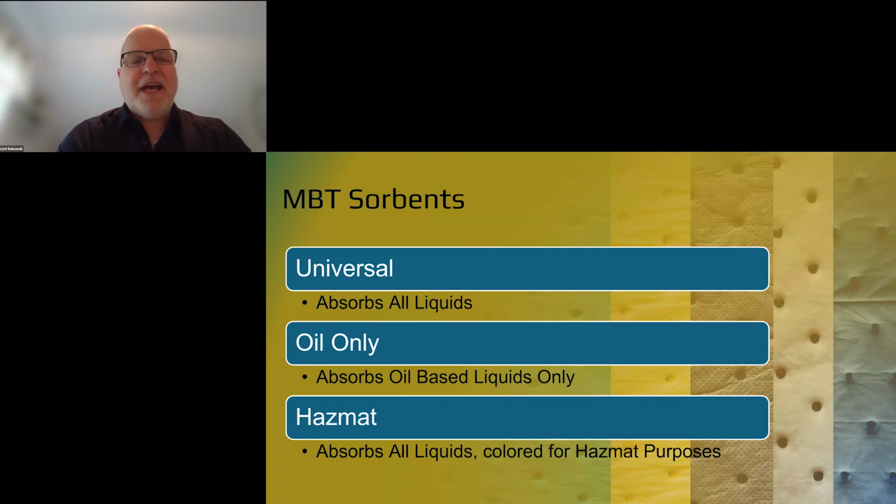Oil only is simply that. It's oil only. 99 times out of 100, this product is white and it absorbs oil-based liquids only, so anything petroleum-based. It'll repel anything water-based or any chemical or solvent. A lot of times you'll use oil-only product in outdoor applications. It may be in an environmental cleanup, or at your facility in an outdoor application like storm drain containment or possibly holding ponds or something like that.